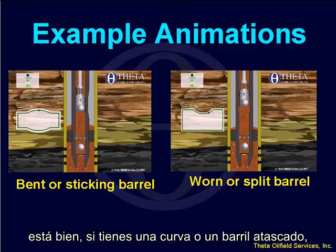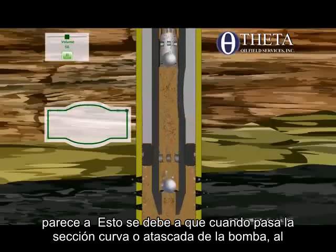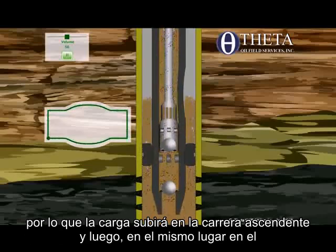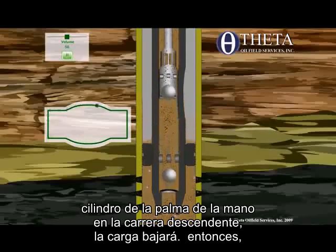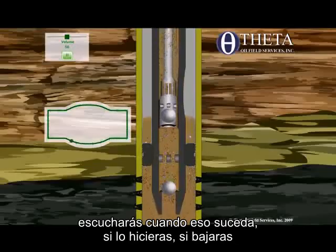Okay, if you have a bent or sticking barrel, you're going to see a card that looks like this, because when you go past the bent or sticking section of the pump, the plunger has a hard time squeezing through. So the load will go up on the upstroke, and then at the same spot in the pump barrel, on the downstroke, the load will go down. And that's exactly the sound you're going to hear when that happens, if you were to go down there.